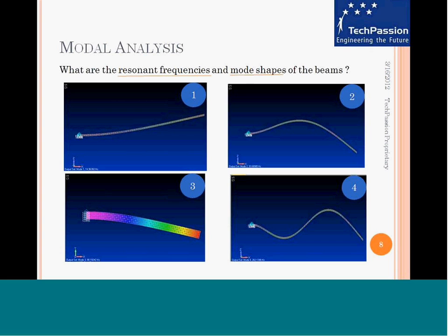One thing that is missing in the modal analysis performed in the simulation is damping. When we are working with a steel beam, steel has a certain material damping. Now when it comes to working with this advanced composite system consisting of carbon fiber and epoxy, the question to ask is, what is the damping?